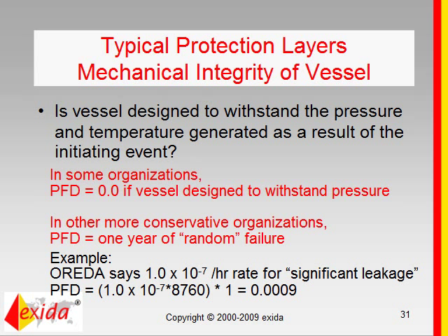So what we typically see is an initial SIL selection with a risk graph or a hazard matrix, resulting in a bunch of SIL 0, SIL 1, 2, and 3, and then an additional, more detailed SIL selection for the SIL 2s and SIL 3s to make sure that these are actually SIL 2s and SIL 3s.